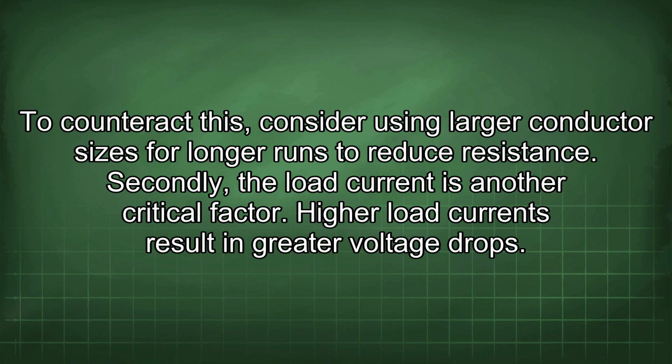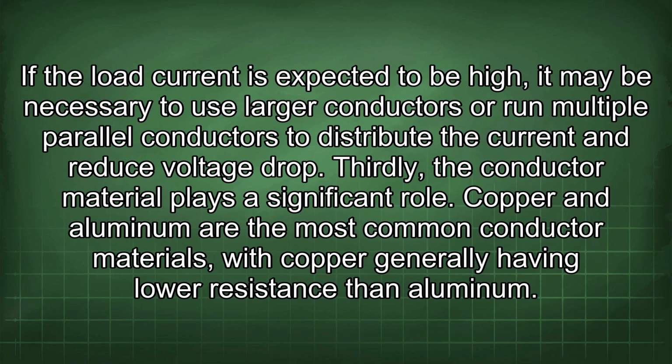Secondly, the load current is another critical factor. Higher load currents result in greater voltage drops. If the load current is expected to be high, it may be necessary to use larger conductors or run multiple parallel conductors to distribute the current and reduce voltage drop.